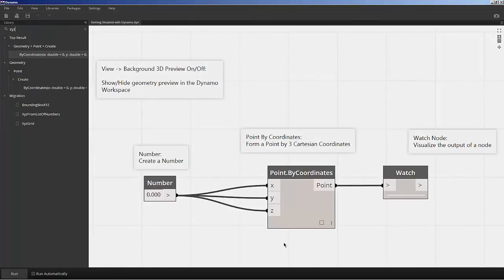The first thing you should notice when opening a Dynamo file is that it does not contain any actual objects or geometry. Instead, a Dynamo file represents a set of instructions for how Revit may automate certain tasks and routines. This set of instructions is clearly outlined in the wires connecting the various elements or Dynamo nodes present in the file. In Dynamo, this collection of elements is referred to as a definition.